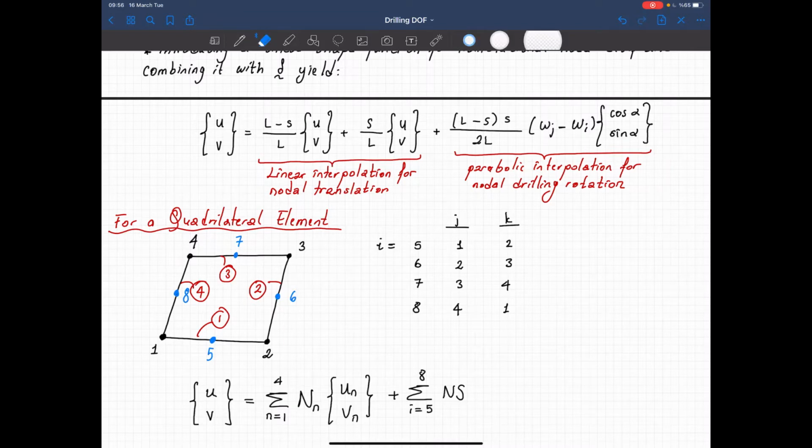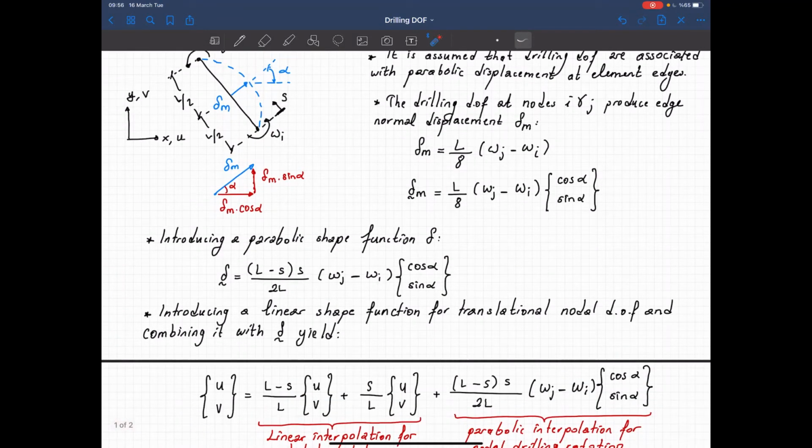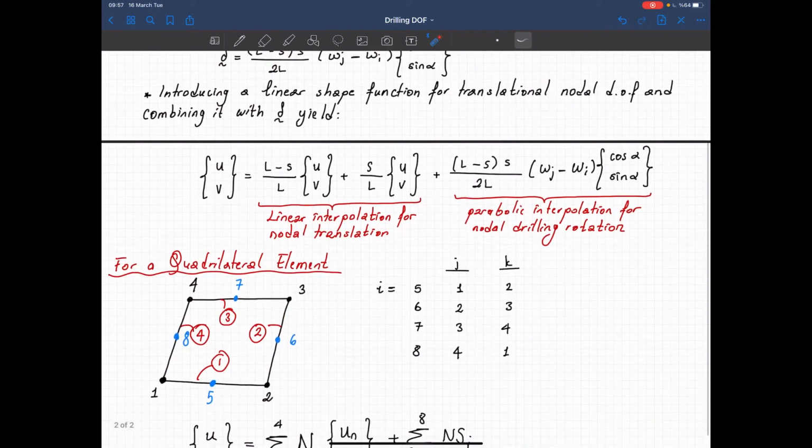Now in this case, I'm using the 5th, 6th, 7th and 8th of the quadratic shape functions, and these shape functions will give me 1 at every mid node. It's like the 2D version of it, and this is the same shape function for this surface.